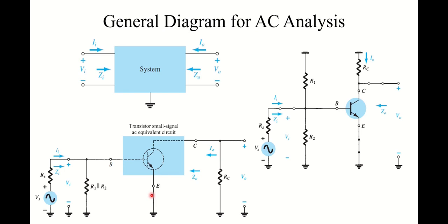Now we will discuss the re transistor model for the configurations of common emitter, common base, and common collector. We will also discuss each approximate circuit of the re model, and why it is a good approximation of the actual behavior of a BJT. First of all, let us discuss the re model for a common emitter configuration. You should keep in mind that the re model of a common collector configuration is the same as that of the common emitter configuration that is to be discussed now.